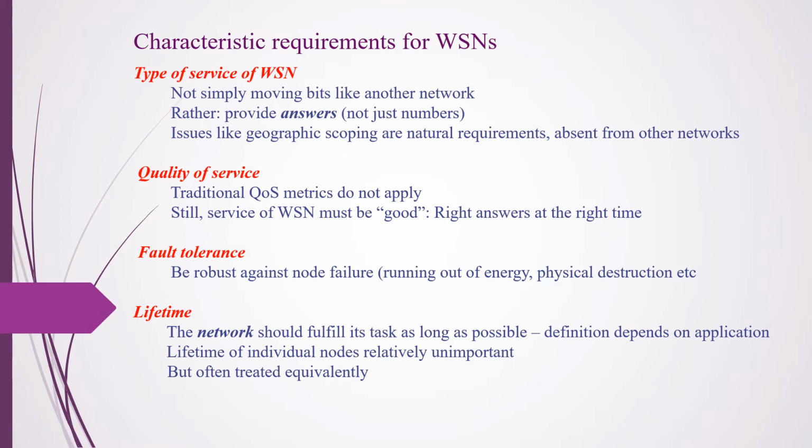The third challenge is going to be fault tolerance. Here, nodes may run out of energy or get damaged, since the wireless communication between two nodes can be permanently interrupted too. So, it is important that the wireless sensor network will be able to tolerate such faults. To tolerate the node failures, redundant deployment is necessary, using more nodes than would be efficiently needed.